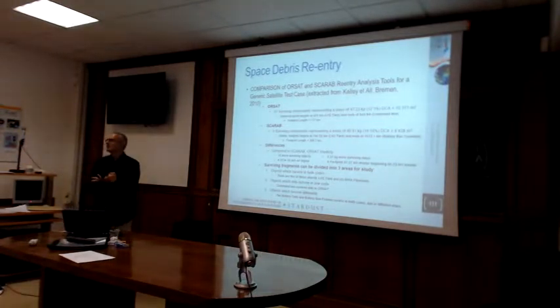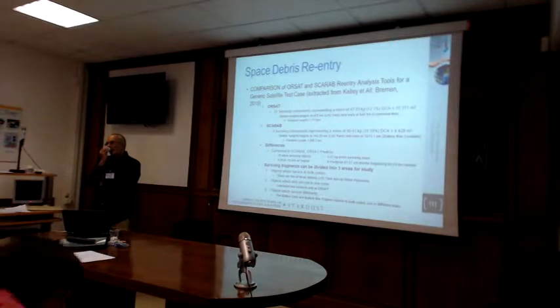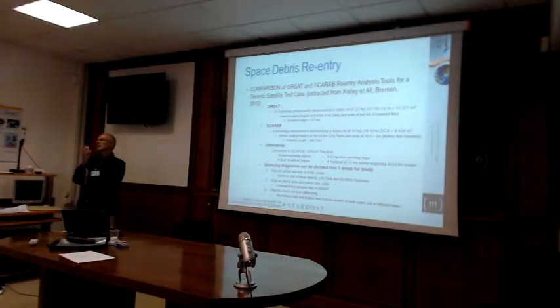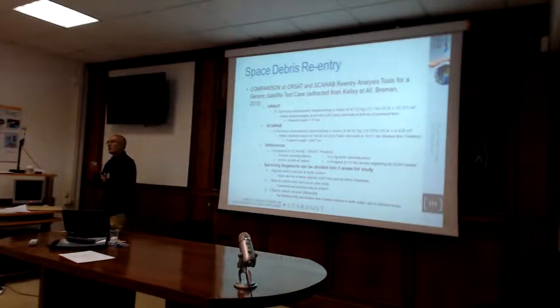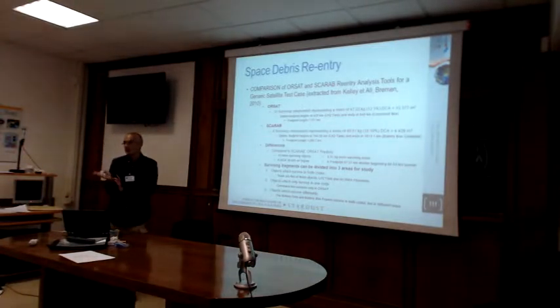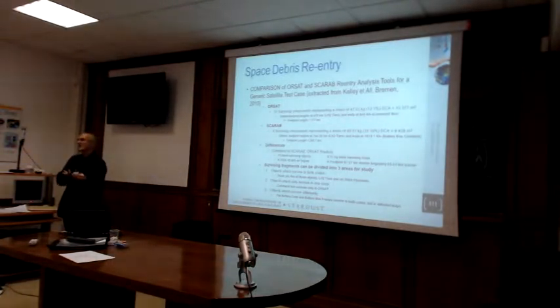Do you remember what the acceptable limit of the casualty area is? 8 square meters. So for one it is inside, for the other one it is outside. It's not acceptable. So that's the problem at the end. Well, but remember also that 8 square meters is a limit which depends on the year of the mission. So it was 8 many years ago, but that's true. If that is the limit, one says that it is fine, and the other one says no.